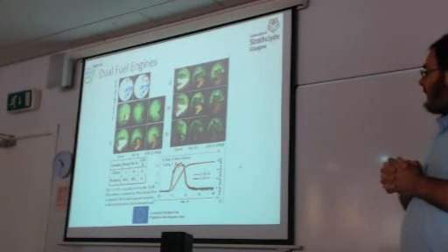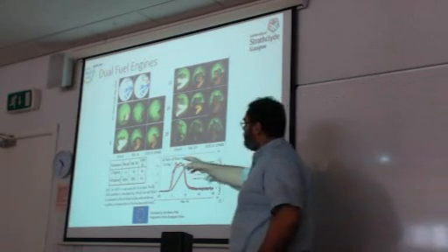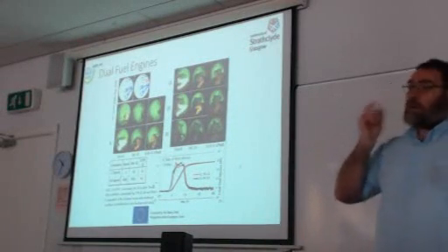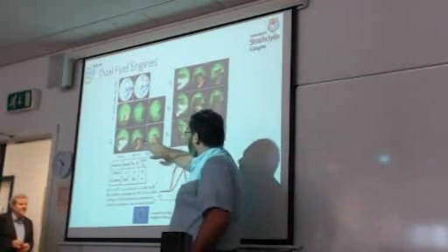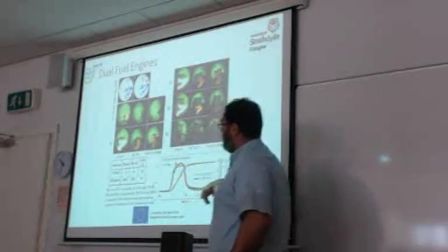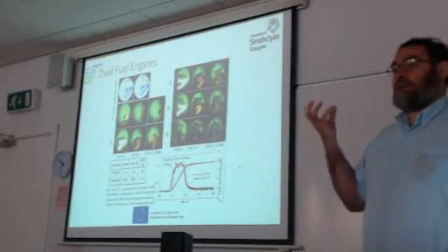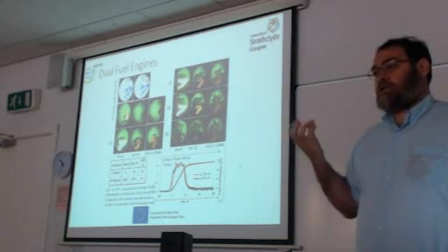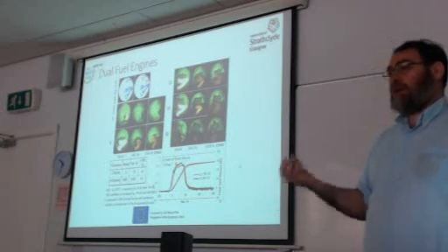And in this case, the disadvantage is that in order to comply with Tier 3, another technology for reducing NOx emissions is required. For example, SCR, selective catalytic reduction, or EGR. And here we also have an example of what happens with EGR and why, of course, the combustion is a little bit different. So we have a standard gas injection, and then we have a gas injection with EGR. You know what EGR is, correct?